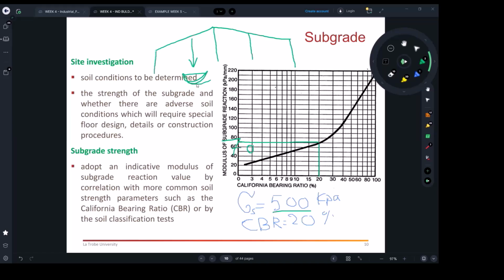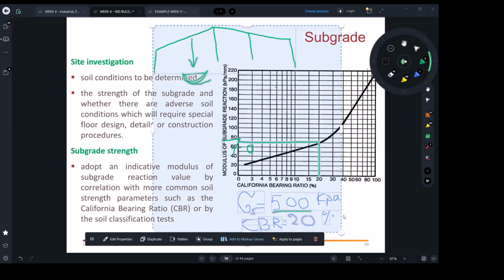Now, where is your role? What's your job here? I know you're not the designer, but you need to make sure these numbers are working together. You can't bring a forklift which is more than this figure, because you may end up settling the slab more and eventually cracking. After they find the 7 millimeters that you calculated, they will make sure the slab can take it safely.